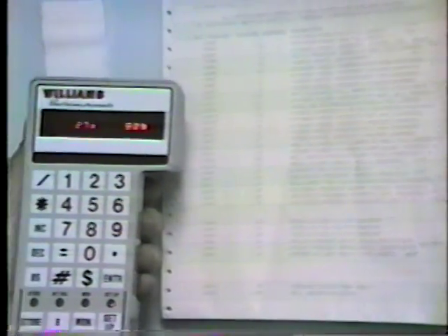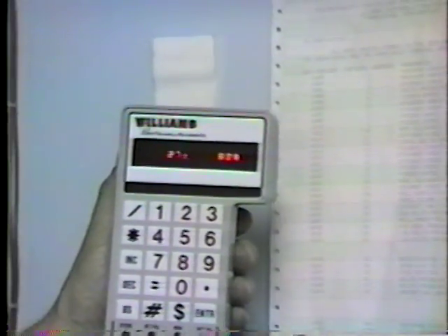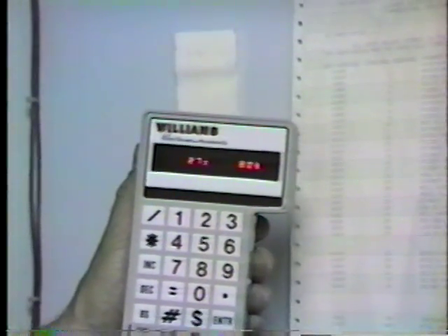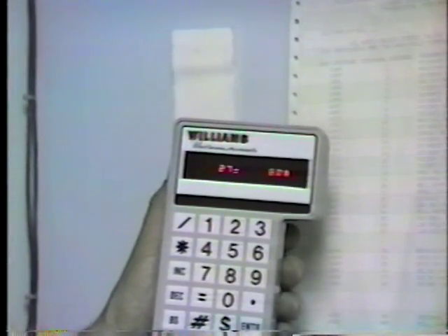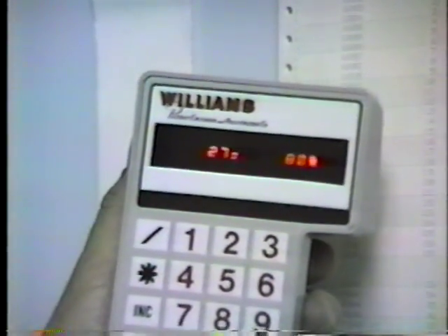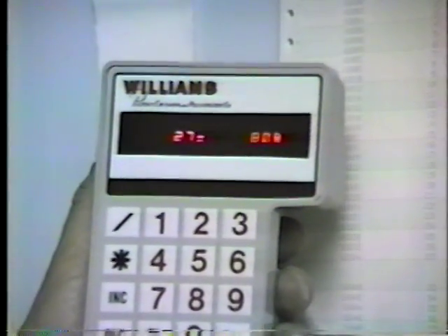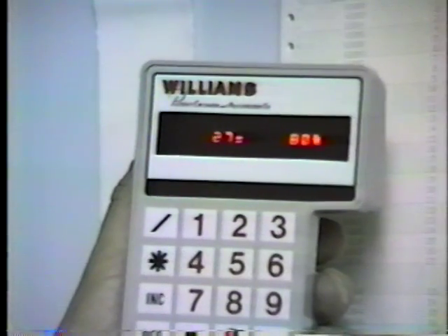26 we already did, that's the low delta pressure startup time. And 27 is the low delta pressure calculated limit. Besides having a low delta pressure switch on the delta pressure meter of the local panel, the computer calculates how far delta pressure is running below target delta pressure. And this is the value that it would allow below target.